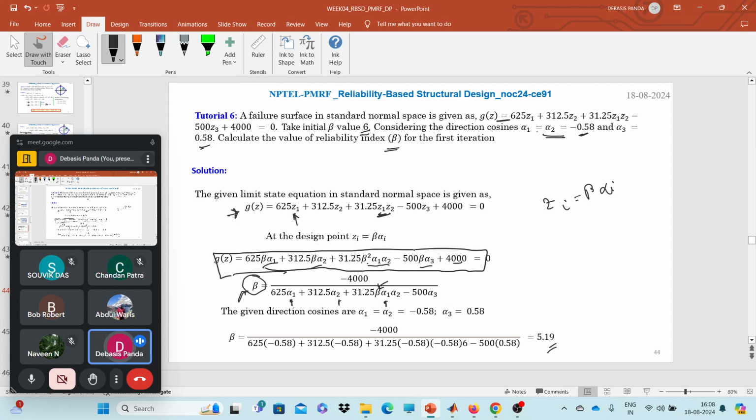If you solve this, with beta and beta here, you will get the root of beta, but that beta is not the optimized beta for you. You need to find some beta that will give you the minimum distance, that means the MPP. Here the initial beta is starting at 6. That might not be the case that your probability of failure corresponds to beta equal to 6.